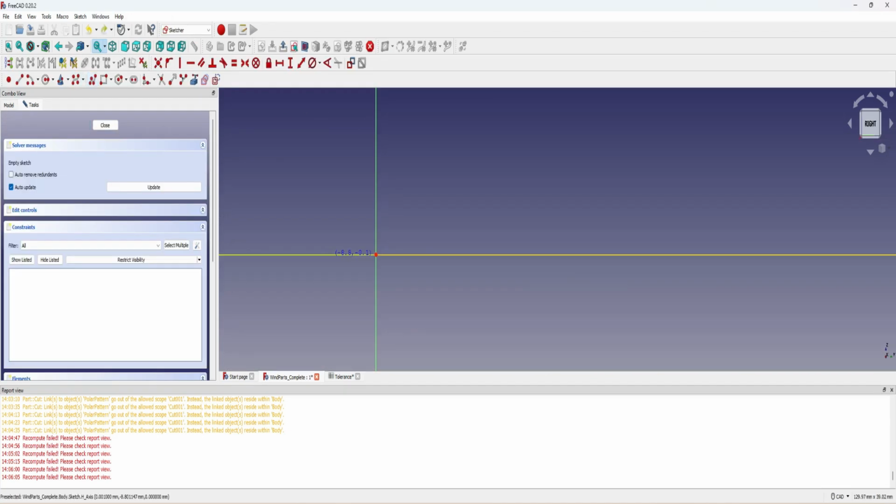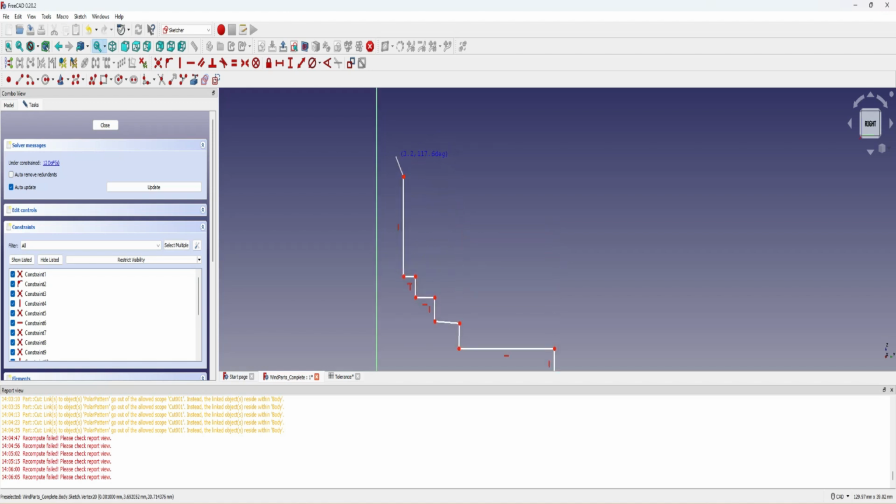So here, when I create the part, it's going to be essentially a cutaway view straight down the center of the part, and it's going to have all the different layers that will eventually be revolved around into the different discs that will make up the whole part. So the dimensions, I'm not going to put in yet, I'm just going to do the general layout of the part, and then I'll use the constraints to set all of my dimensions up.